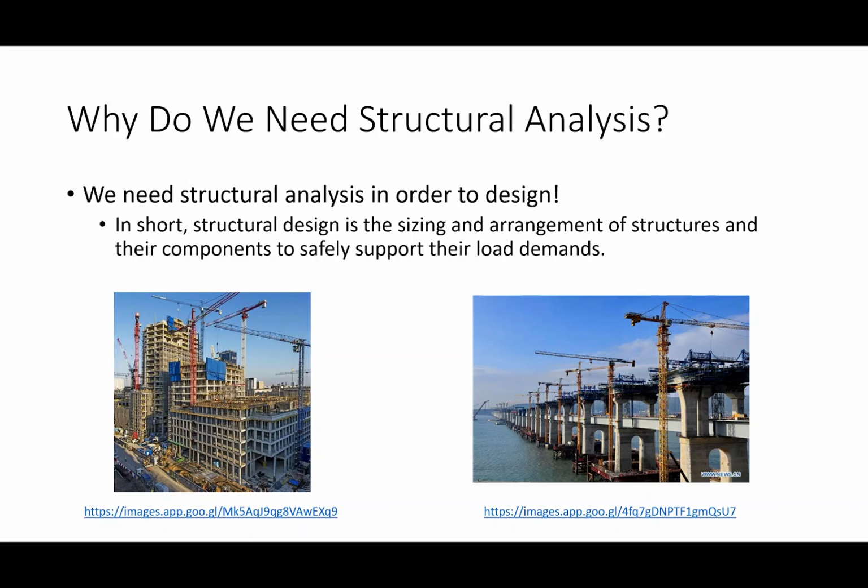We care about properly analyzing structural systems because it is our job as civil engineers and structural engineers to design those systems. So what is structural design? Structural design is arranging and sizing all of the components of a structure to safely resist that demand. Let's say we're talking about a steel frame, the new Brad Smith business building. Some structural engineer had to design the beams, the columns, the connections, the bolts, the welds, the foundation, all of that in order to safely support all the loads that frame was going to be subjected to. That's structural design.